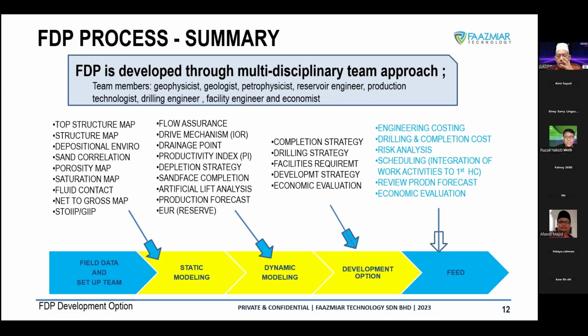And of course, after some time, for example maybe after 5 years, the pressure in the reservoir starts to deplete. So we have to think about how to lift the oil up to surface. In Peninsular Malaysia, normally we discover our oil reservoirs at shallow depth, maybe just slightly over formation pressure. So when you produce the well for about 6 months, there's no natural flowing anymore. So for most wells in our area in Malaysia, we are using artificial lift. They call it the gas lift system.